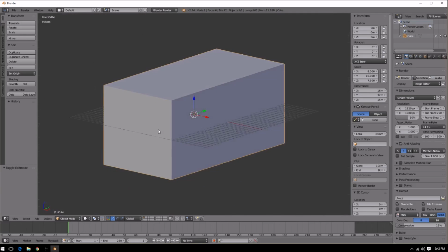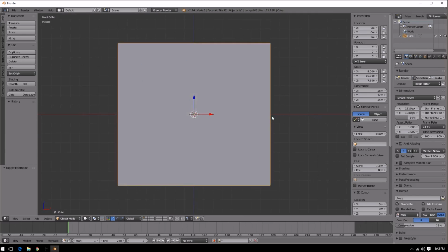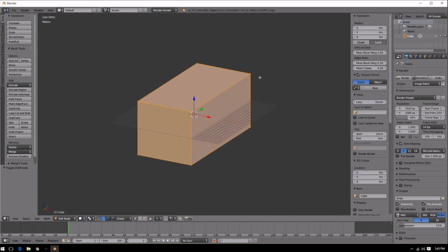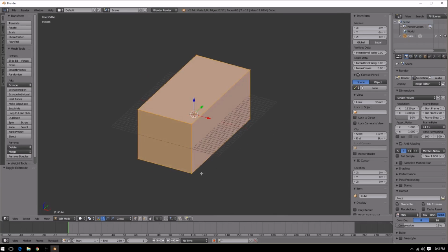Now the next thing we want to do is half of our building is currently underground. As you can see by this red line as our ground demarcation, everything below this is going to be underground. So we want to raise this entire mesh up. I'm going to select this mesh, hit tab to get into object mode, and notice how when you first select an isolated mesh, when there's only one thing here, everything gets selected. So I don't need to reselect everything.